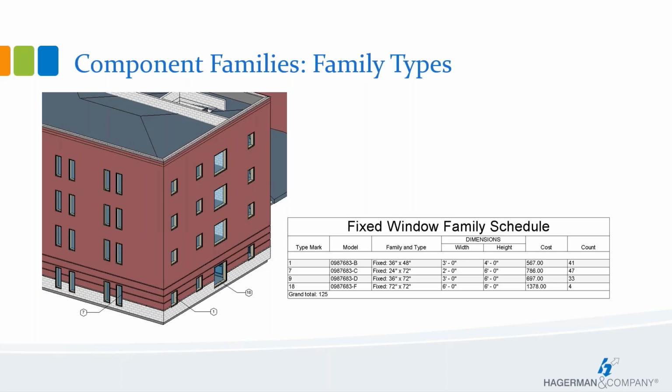Another thing that is super convenient is that I might need a new size while I'm working on a project. If that ever happens, I can easily make a duplicate of an existing one, change some parameter values, and instantly have a new family type without even opening the family editor to add the new type. So this new type can just live right inside your project file. Very convenient for new users who are not really familiar with the family editor yet. You could just create the new type right inside of Revit.